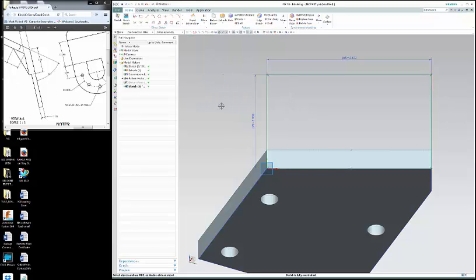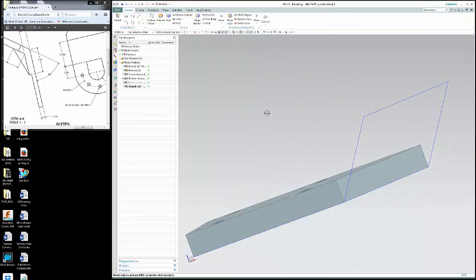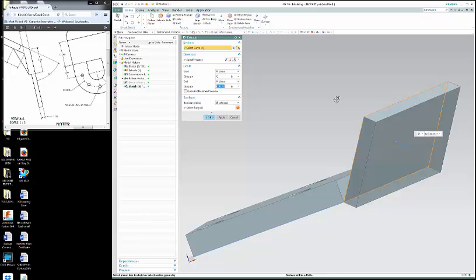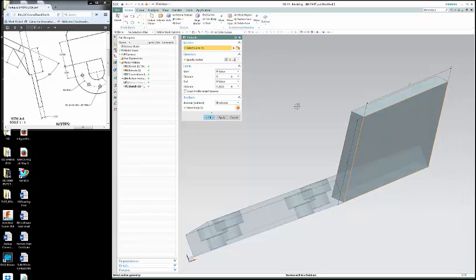Actually, the sketch is fully constrained. You can see that at the bottom. So we'll finish the sketch. Rotate that around and see what we've got. And we'll extrude. Select a curve. We'll pick this here. It's going the wrong direction. So again, you could either double click this, or you can come over here and click that. Okay, and we want that to go 0.5.